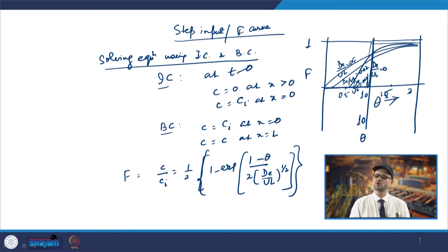as it is 0 it will be the plug flow, and as it goes towards infinity you will have the value for the well mixed flow. It shows like this because the dispersion has started here itself, whereas for 0 it has not happened, and at the mean residence time of theta equal to 1, that is the theoretical mean residence time, all has come out with concentration of 1. So, that is the significance of the dispersion number, or the vessel dispersion number.